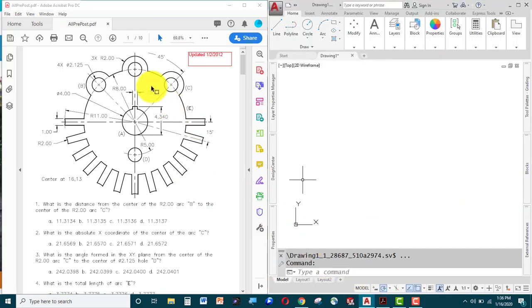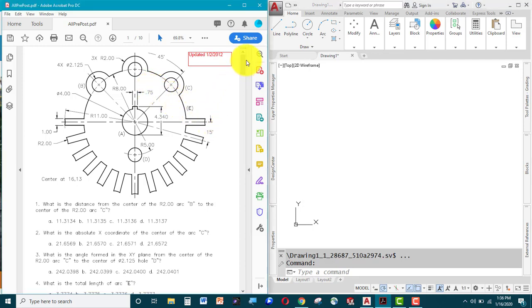We're going to look over here, and the thing I want you to look at is the fact that there is a repeatable pattern. Always, when using CAD software of any kind, look for repeatable patterns and take advantage of that. In this particular case, we've got two repeatable patterns. We've got these arcs that repeat. We've also got these tabs that repeat.